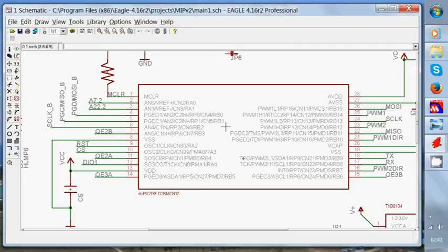For example, if we take pin number 4, it has an option of program data, analog input 2, counter 2 input negative, remappable pin 0, identified as remappable pin 0, change notification interrupt number 4, or a generic port pin, port B, 0th pin.